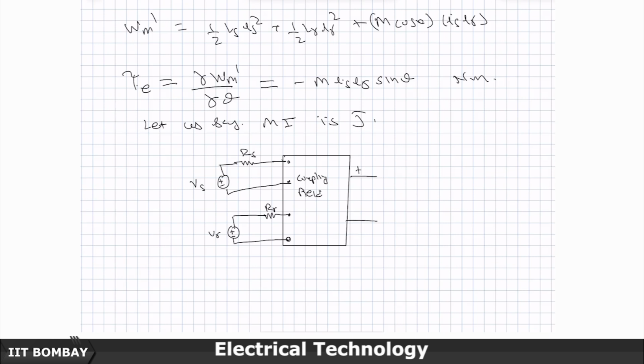And this side represents the mechanical part of it. So, you have plus minus, the variable of interest here is theta, and you have this moment of inertia block, the work gets done out of this. Then you have a damping block indicated by B, and then you have a spring block with spring constant K, and you have the applied mechanical input as Tm.